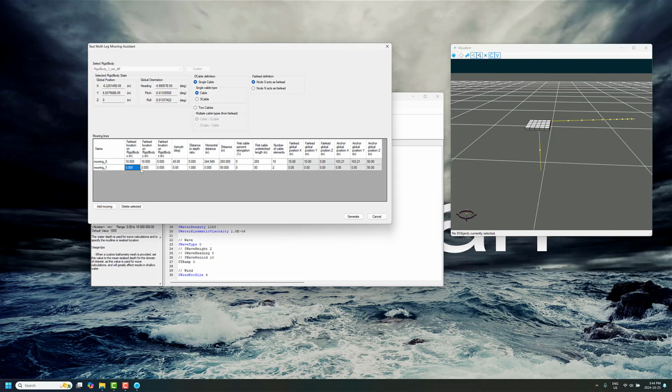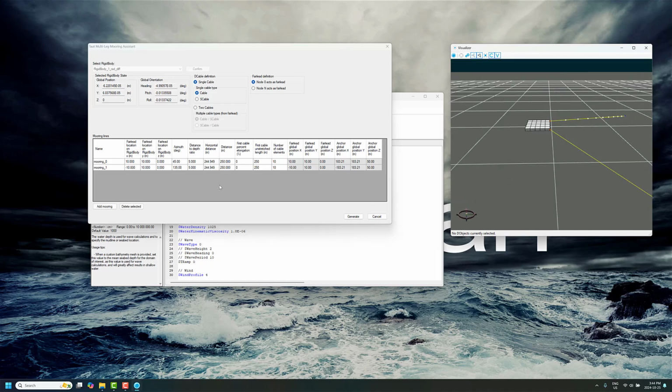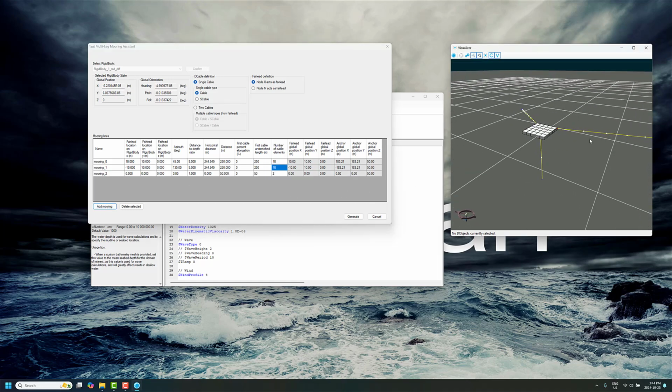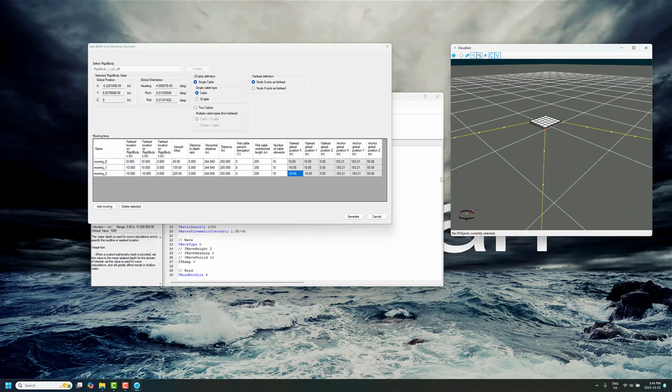We'll do the second mooring line here. Let's see, where's my X there? So we want to do minus 10, 10, and 135. And I can adjust the elements later as well. I do like to have a few elements in there just for visualization. Those white dots are the nodes in the finite element mesh. And we'll go minus 10, minus 10, azimuth angle of 225, 5, 10, and there's the other mooring line.